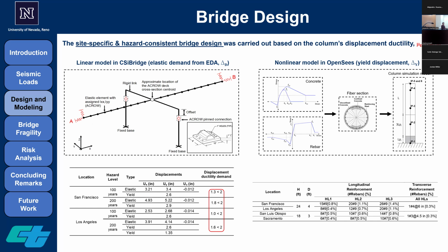I haven't seen any slide. We had one pushover curve on it, but in a report the displacement capacity could be shown. I could do so, but here we're just reporting the ratio. But since it's not an essential bridge, according to Caltrans definition, we were able to relax these values a little bit. That's why you see such a difference, and it's primarily because of the contact with Caltrans in a different part of the project.